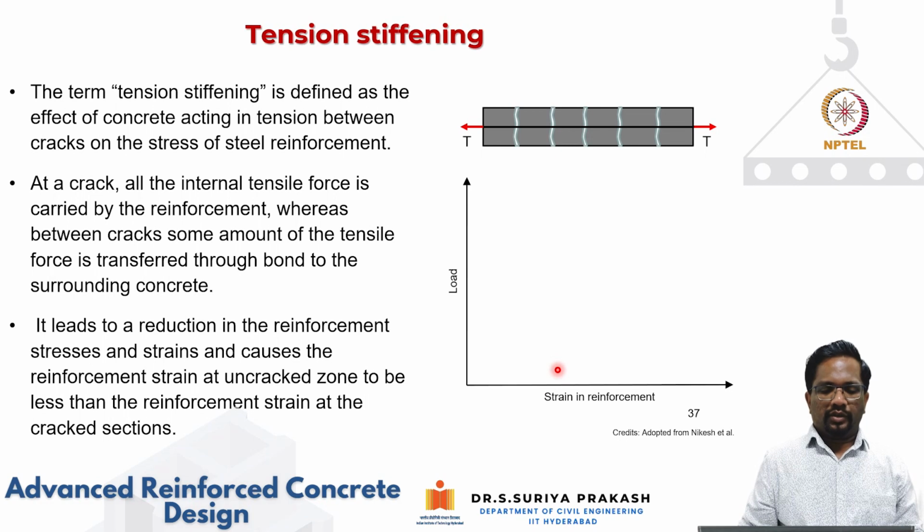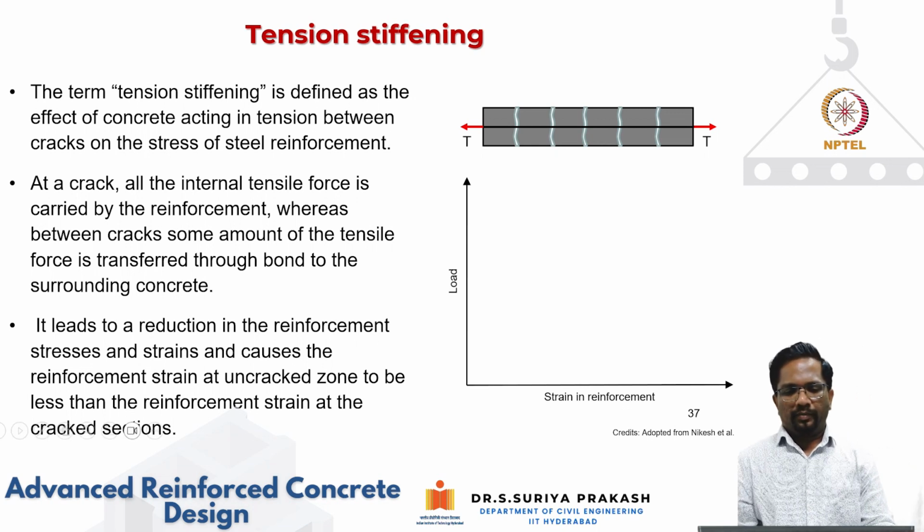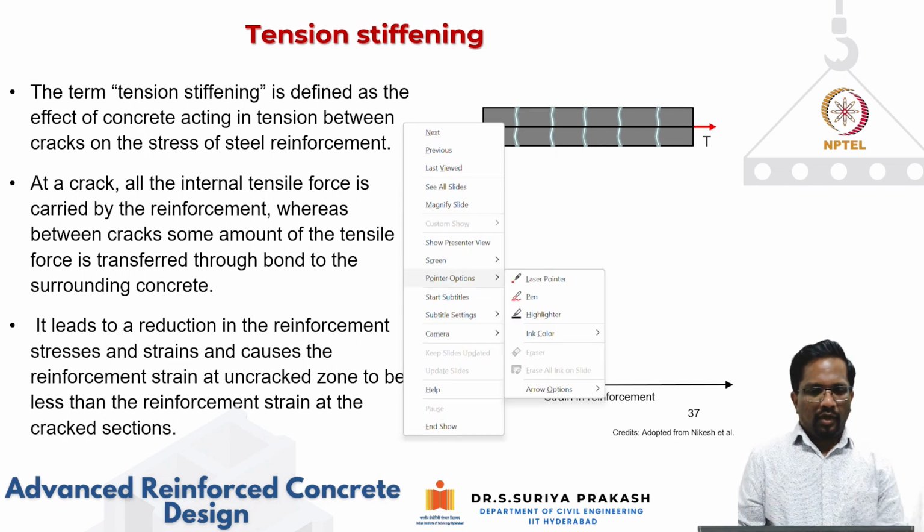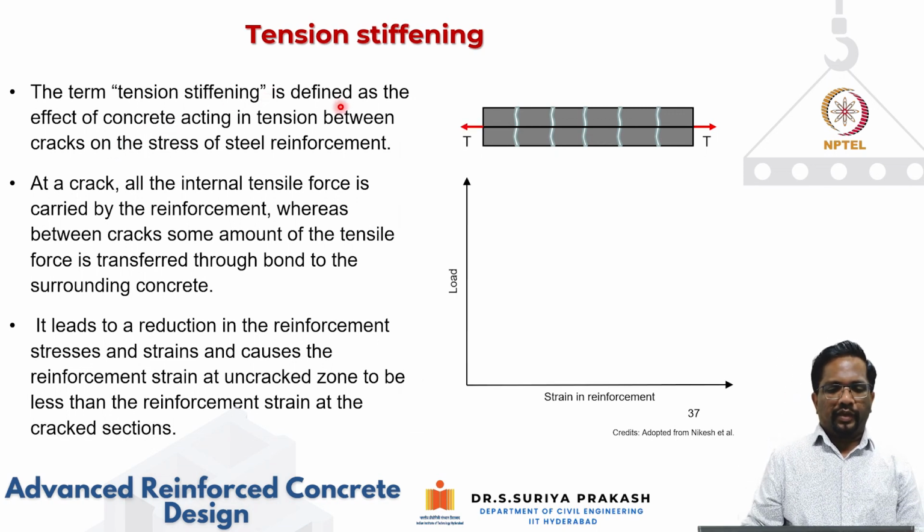Okay. So this tension stiffening is a phenomenon. Again, it's a very important phenomenon. It is defined as the effect of concrete contributing in tension between the cracks on the stress of the reinforcement. So if you take a bare rebar, and let's say this is a concrete prism reinforced with one bar, and I subject this prism to tension, what will happen is